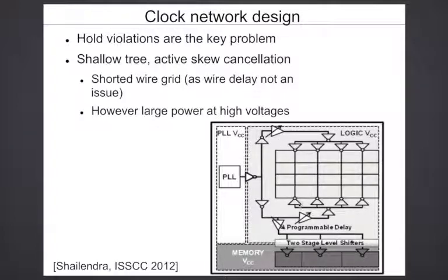but I would imagine that they are doing it once during chip bring up. In the beginning, you set it, and that's it. You don't keep adjusting it during the lifetime of the chip. Okay. Changing voltage and temperature, it may change. It may change, yeah. So when that happens, if that is a large change, then you have to keep adjusting it